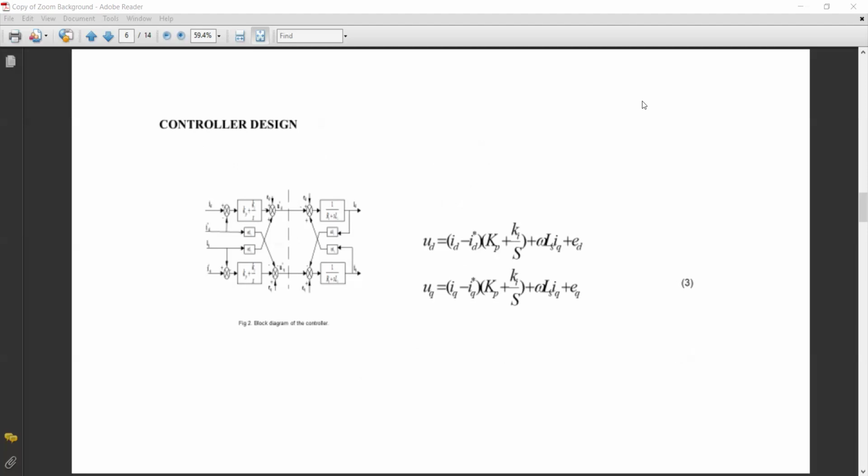in equation 3, where Kp and Ki represent the proportional and integral coefficients of the PI controller, which are respectively given in the circuit. From equation 3, the present configuration shows a closed loop involving the currents ID and IQ within the system. However, the control system currently lacks interaction with the output voltage on the DC side.